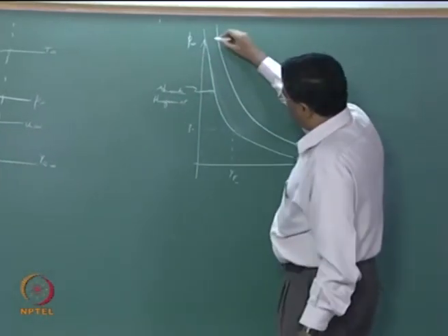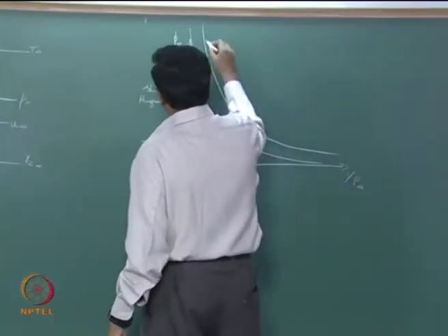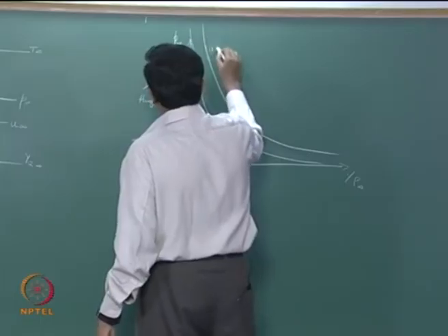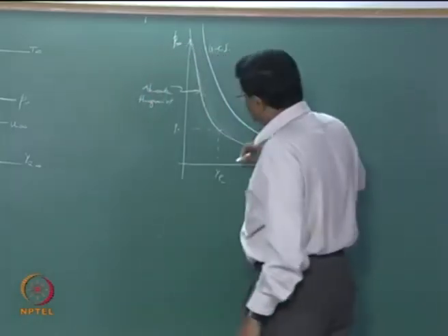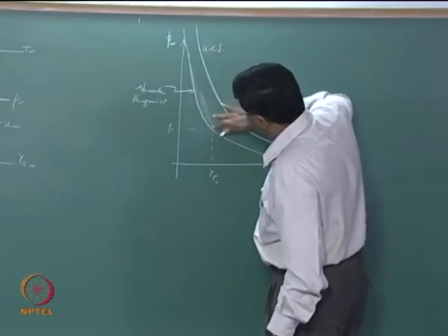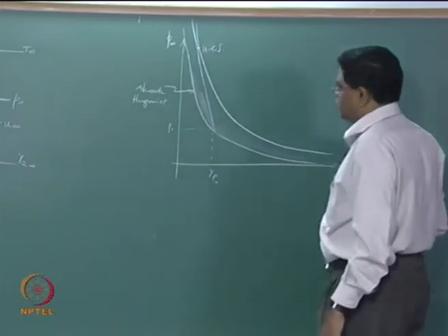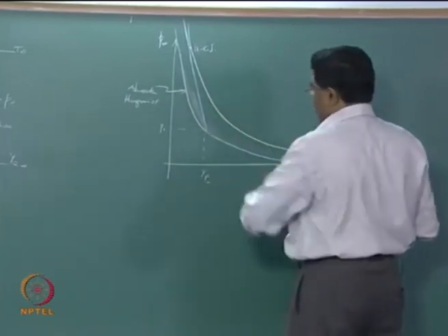And we are looking at the Chapman-Jouguet wave, so that's the UCJ point, and that means you are looking at a tangent Rayleigh line to the actual Hugoniot with the full heat release.